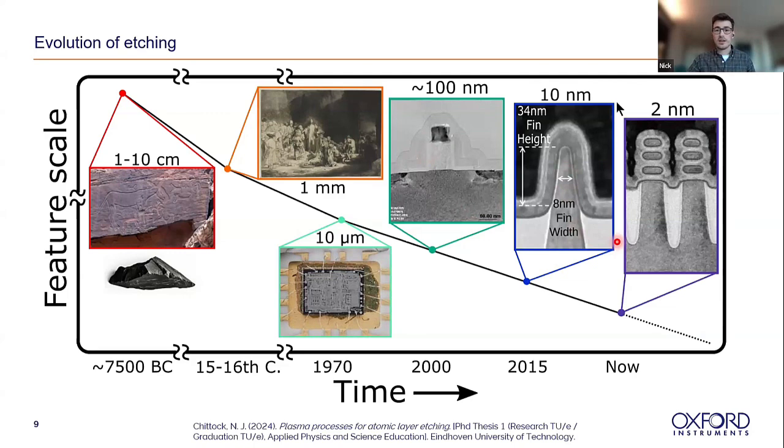So you can see here the gate-all-around structure, which is the next progression beyond the FinFET. And even beyond this, people are looking at things like fork sheet structures and complementary stacking, so basically stacking your NMOS and PMOS on top of each other in this gate-all-around. It's incredible what people are planning to do. And what's interesting is the etch process is going to be integral to all of that advancement as well. Including how it's helped us get to this point, it's going to help us get even further again.